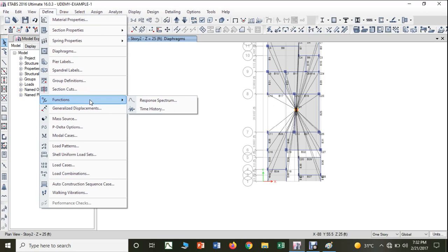So if you consider any time, the magnitude as well as the position of that load will not change. It is going to remain stagnant. So we call that static. And if I am doing static analysis, the load we consider on the building or structure will remain the same throughout our analysis and design. It is not going to vary over a period of time.